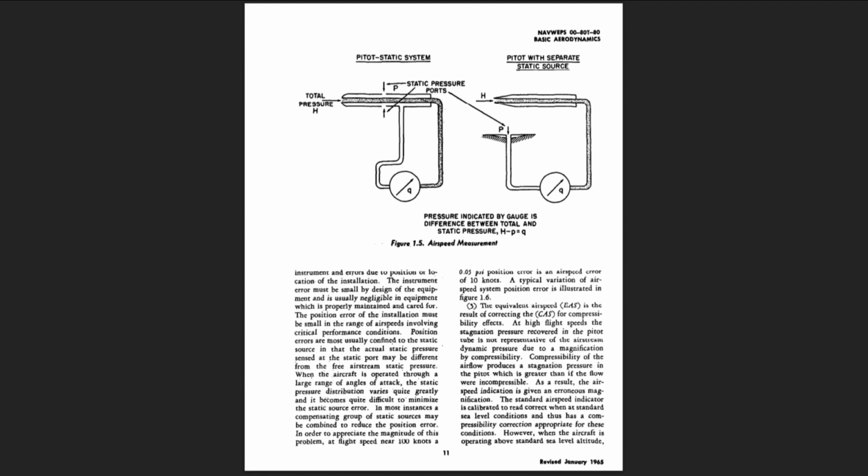Actually, there can be many conditions of flight where the airspeed indicator does not truly reflect the actual velocity through the air mass. The corrections that must be applied are many, and listed in sequence below. 1. The indicated airspeed, IAS, is the actual instrument indication for some given flight condition. Factors such as an altitude other than standard sea level, errors of the instrument and errors due to the installation, compressibility, etc., may create great variance between this instrument indication and the actual flight speed.